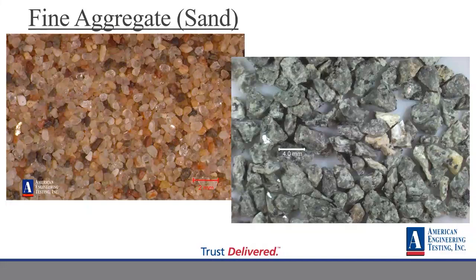So that previous slide was for the coarse aggregate. The fine aggregate, we also do thin sections for fine aggregate, but obviously that's a lot smaller material and it would be a nightmare to do that many thin sections. So what we do is we make an epoxy plug of the sand grains from each of the sieve sizes, and for concrete sand, they typically use a number 4 sieve, number 8, 16, 30, 50, 100, 200, and then whatever's below the 200, called the pan material.